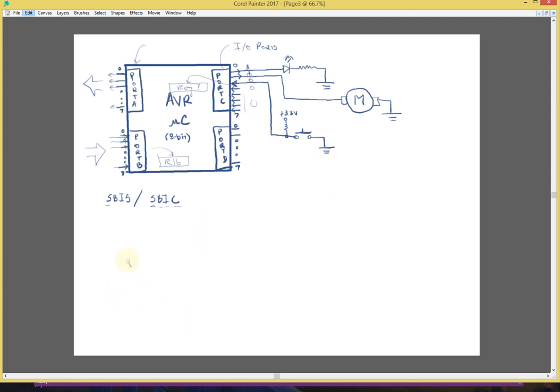Suppose that I have a loop, and I want to turn this light on whenever I push this switch. So I'm constantly reading the switch, and the switch is 0 when pushed, because this is active low. So 0 means I pushed it, and 1 is going to read high when it's not pushed, or depressed, however you want to say it.